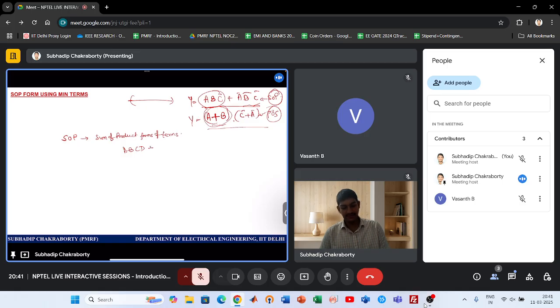them with other terms. So these form a term, but they are product terms, and then they are added. The product terms you add either in the true or the complementary form to form the Boolean expression. So they are known as min terms. In SOP representation, where you have the sum of product terms, the product terms individually are referred to as min terms.